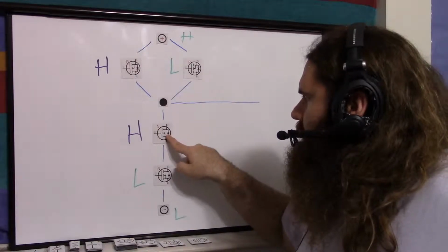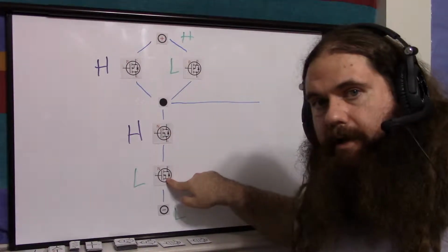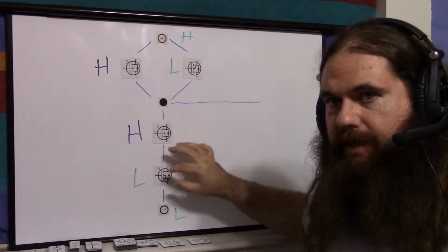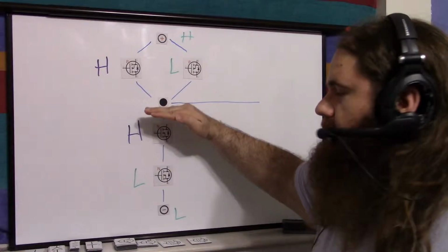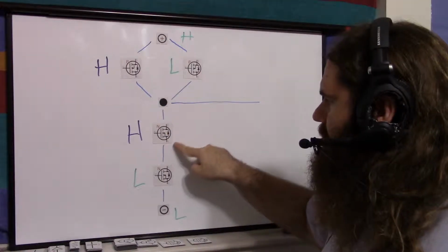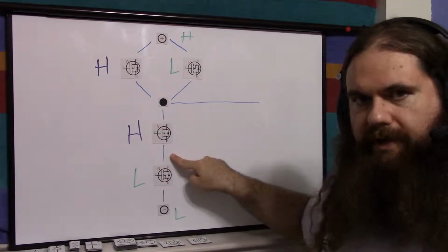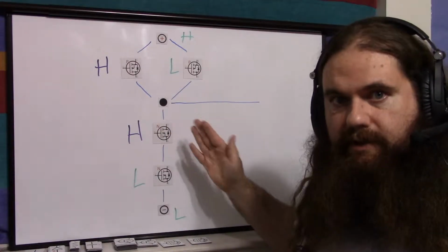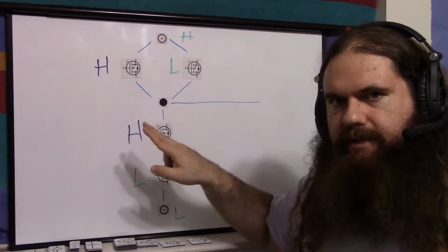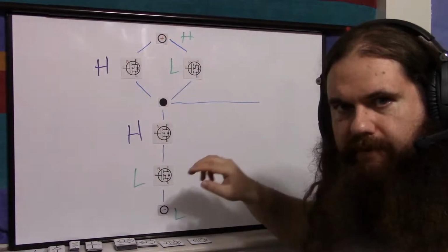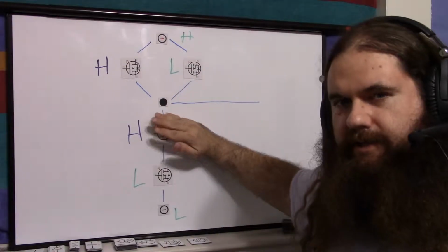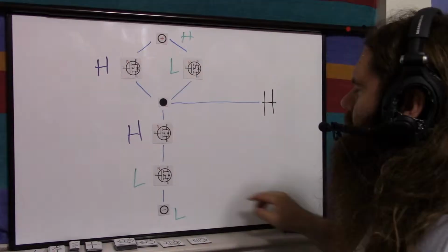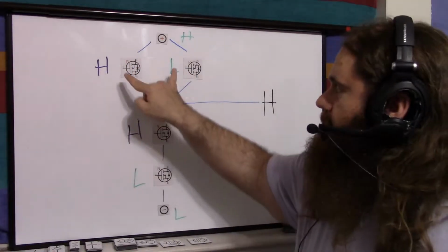And what happens here? This N is on, but this N is off because this one's getting a low. So they're in series. They have to both be open for the negative to connect through. So this is closed off. This is N. Technically, this current can get all the way through to this source in between the two, but it can't get through this one, so it's still nothing happening. There's no base to emitter, anything going on if you hook them up in reverse. No resistors, none of that. It's still effectively closed off from negative, so you're only getting your high through the P. And you can see, obviously, if we switch it, we'll have the same thing.